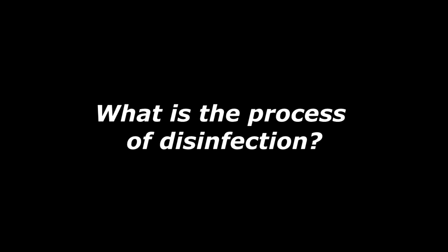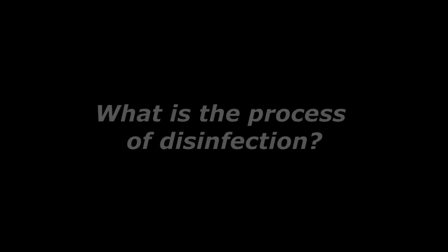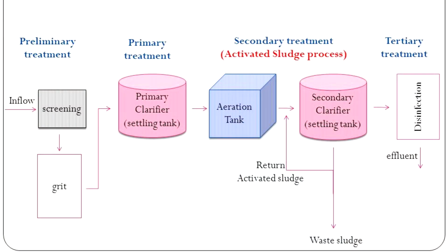Then the clean water that flows out the top of the clarifier is sent to the next step, which we are calling disinfection. Basically, disinfection of wastewater can be accomplished in one of three ways: chlorine, ozone, or ultraviolet disinfection, known as UV. Each process has its benefits and drawbacks, with each being used commonly throughout the world. Now I will choose chlorine.